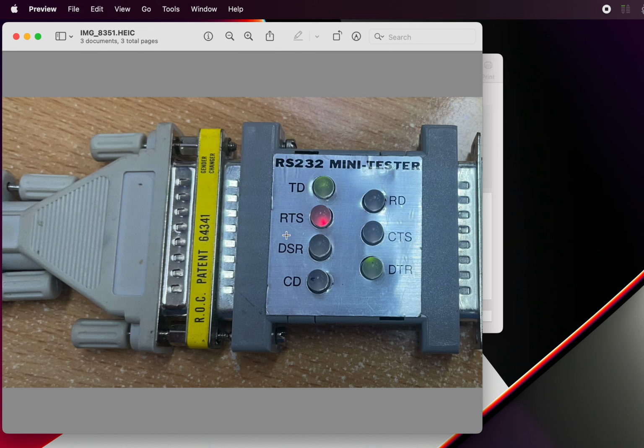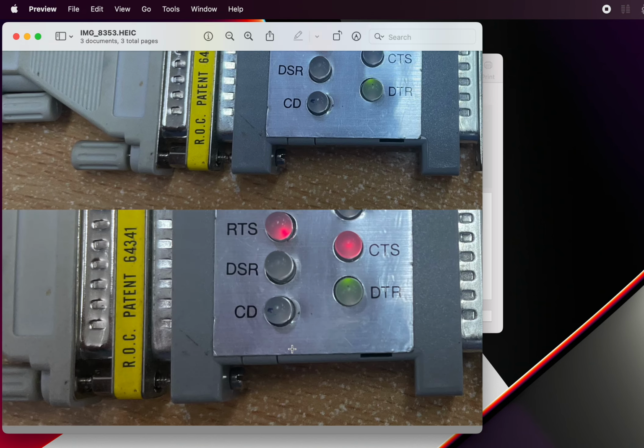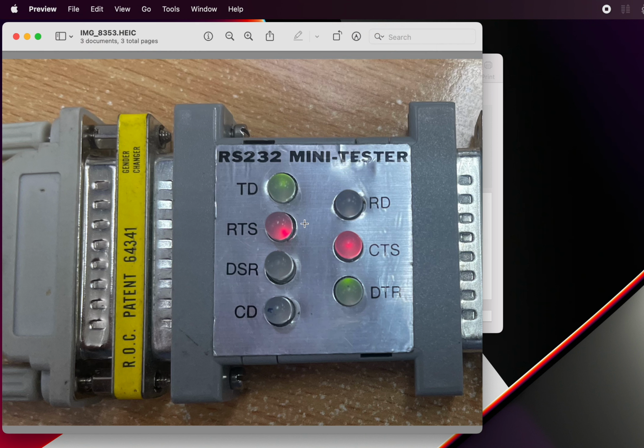When you test your actual circuit, the reason why I've put that RTS in is it enables you, rather than needing any other circuitry, to just need a switch, and via that switch, you bridge the RTS across to the CTS. So when you bridge RTS to CTS via the microphone switch, the CTS line will come on when you press the switch, and then it'll look like this.